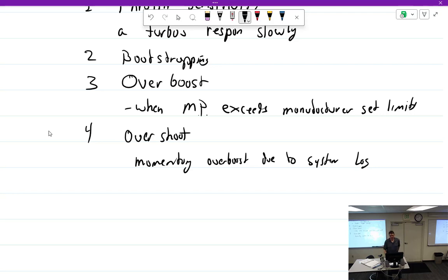So that'd be overspeed, but it's the same thing. I can have an overspeed or an overshoot. If I take off on a constant speed prop and the governor's not adjusted normally, or somebody adjusted the governor to a tachometer which is way off, and come to find out you've been running around at 200 RPM over this whole time, that would be an overspeed.